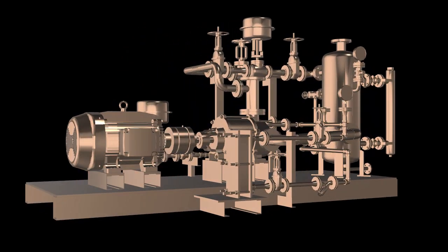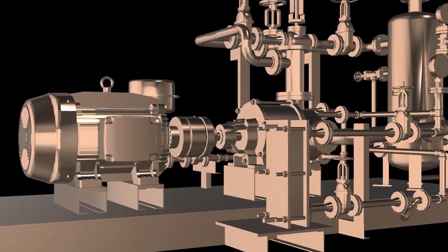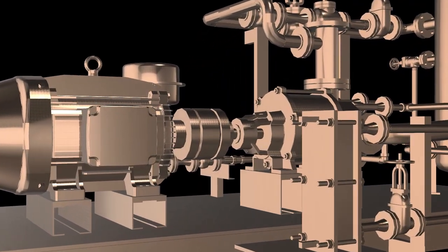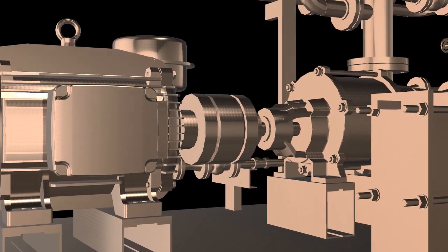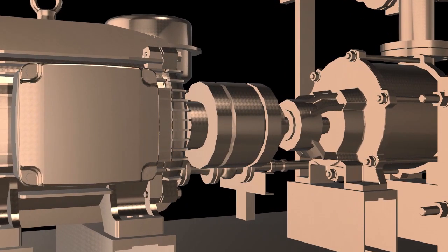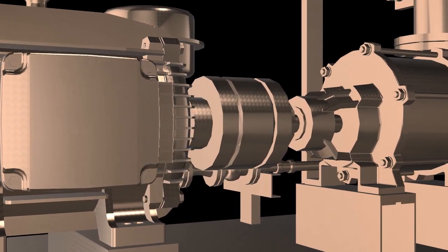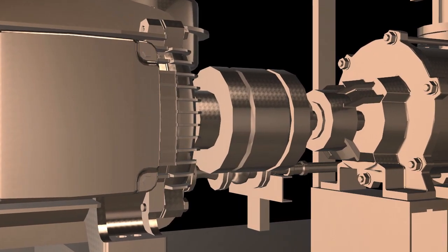Benzene is a hazardous liquid that is highly volatile at room temperature and evaporates into the air very quickly. Its vapor is heavier than air and may sink into low-lying areas, thus affecting the classification extent. The most likely source of release in this process is the pump seal.